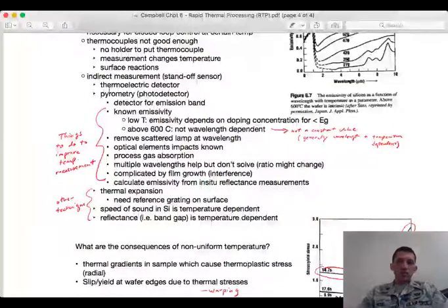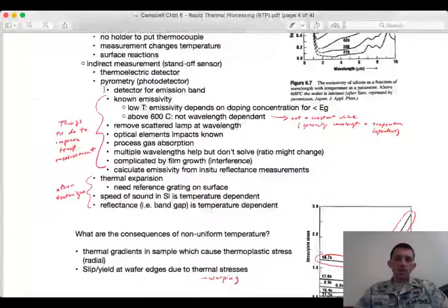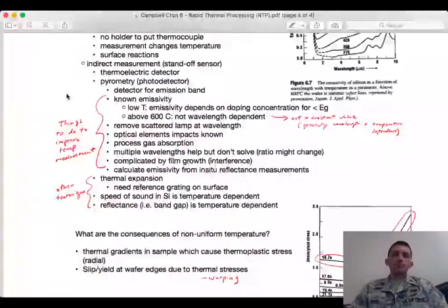So you can have materials that change their resistivity and use that as a means for a detector, or you can have a photodetector that actually is another silicon device that absorbs the photons, creates electron-hole pairs, changes the conductivity, and you measure that as a change in the current that flows through the device.